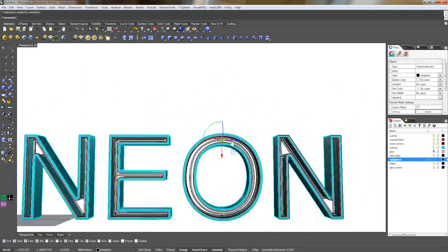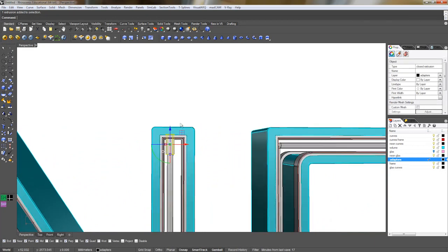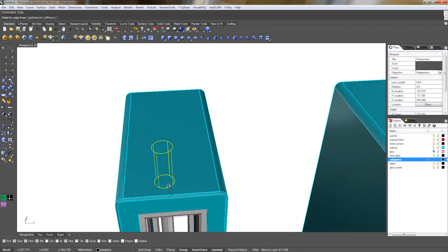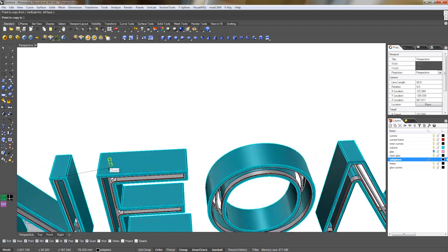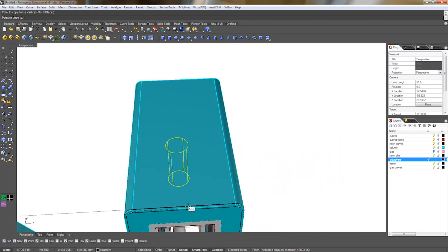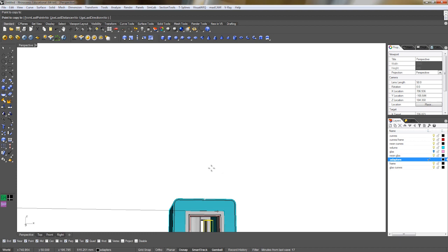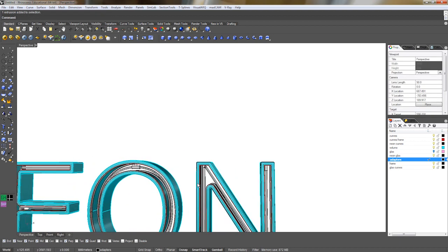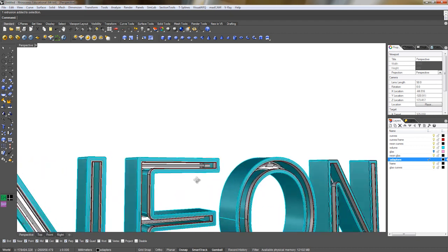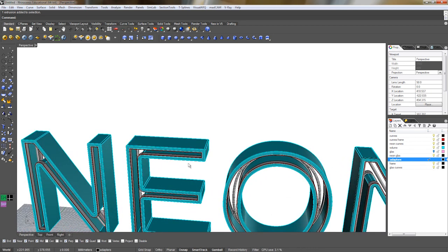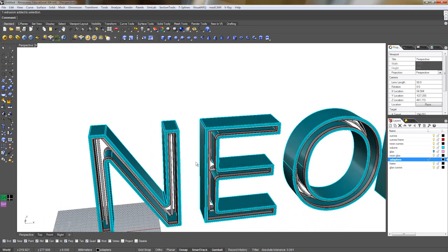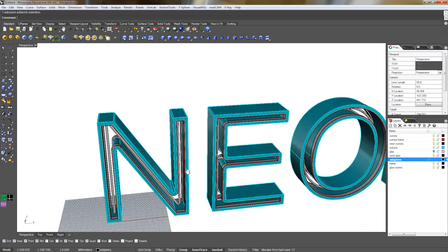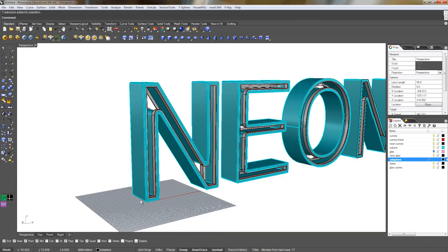It looks okay. And we're going to copy and rotate it like this. Okay. And of course we're going to copy it from the end for the other end. Just take the midpoint here. If the snapping is not working for you, you probably need to press this button here to actually get the snaps. Okay, so we got the adapters. They are on the right layer.